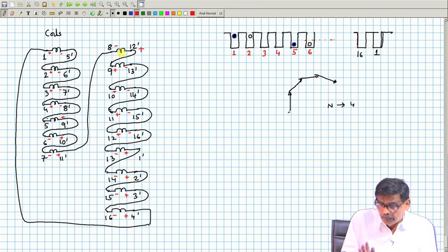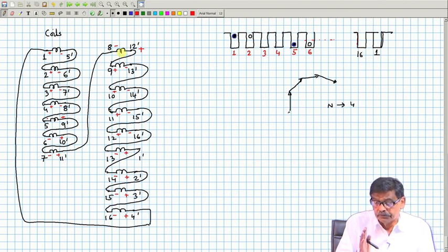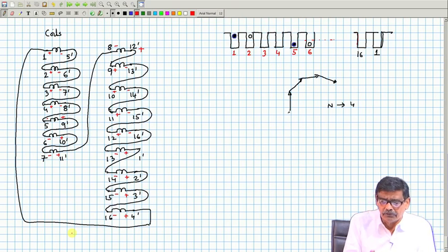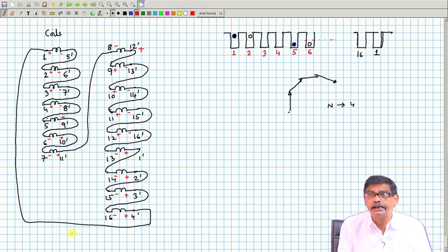So, I stop here today to conclude that the armature winding of a DC machine that I am discussing is not complete. I told you there will be several coils. Coils are to be placed in slots, and all the coils are first to be connected in series and the circuit is to be closed. The question still remains: that is fine, there will be no circulating current, but my goal is how to get DC.